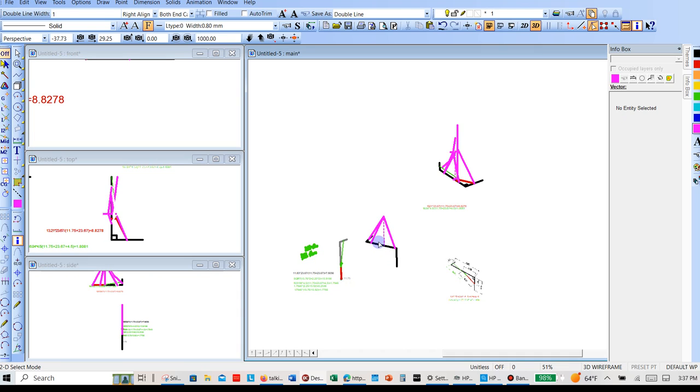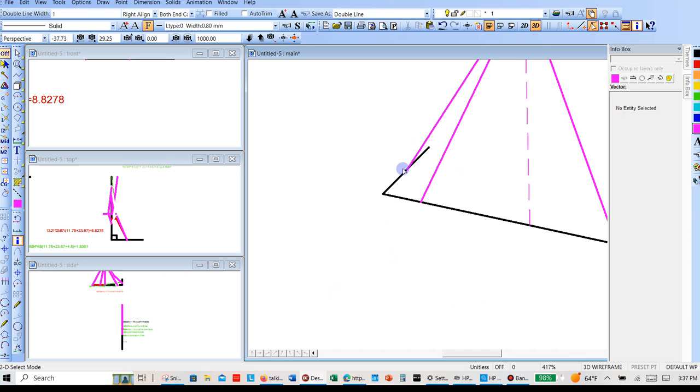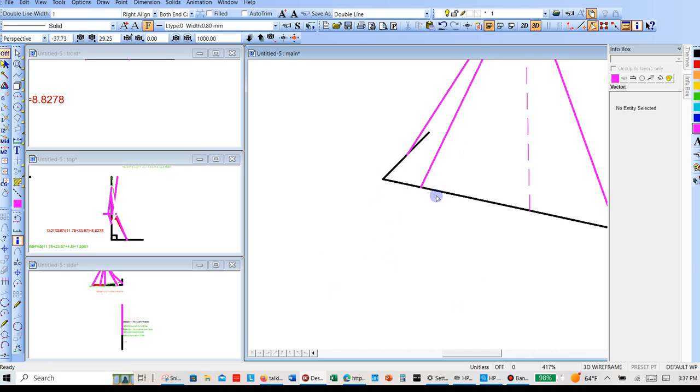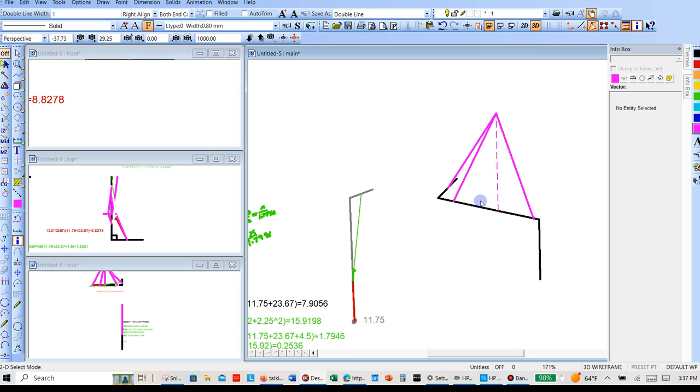Almost, if you just choked it so that the choke slings were on the edge, but you can't do that because it's dangerous, right? You can't choke back more than, what do they call it, choke back. You can't have that choke back like that. So you just need to throw an extra little chain fall or something, an adjustable sling or a turnbuckle on the back leg right there to plumb it, to level it out. It would be pretty level, but it wouldn't be 3 inches off. You'd probably be hanging at 15 degrees or 10 degrees.